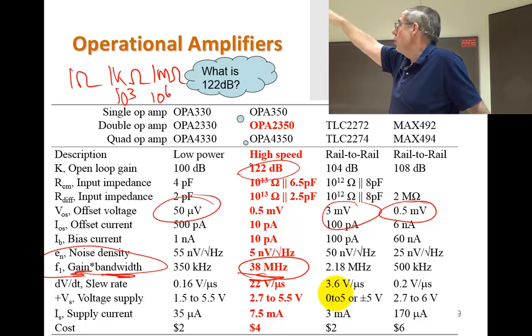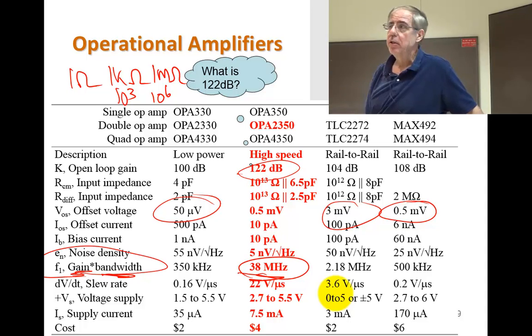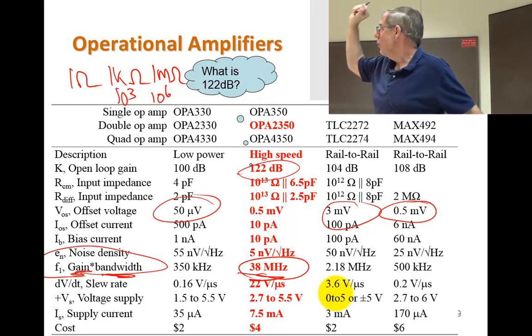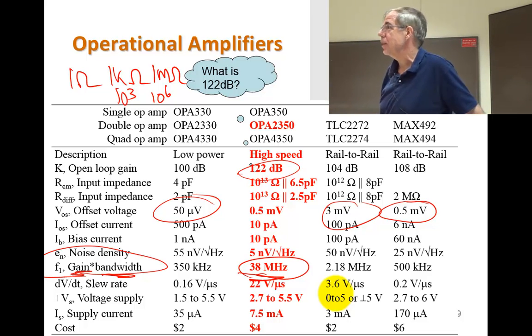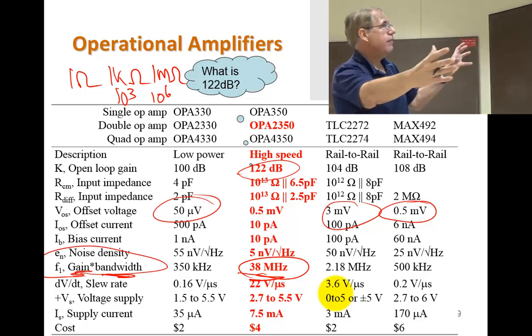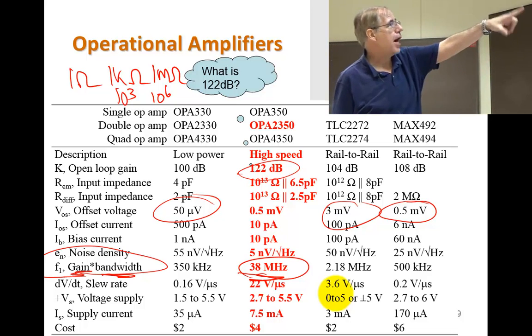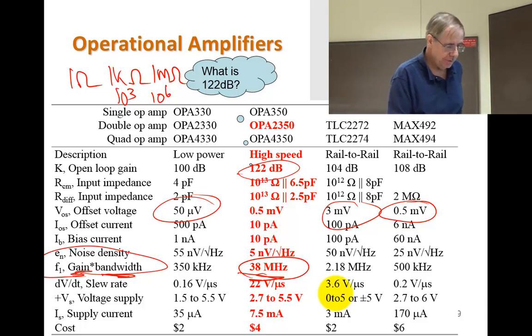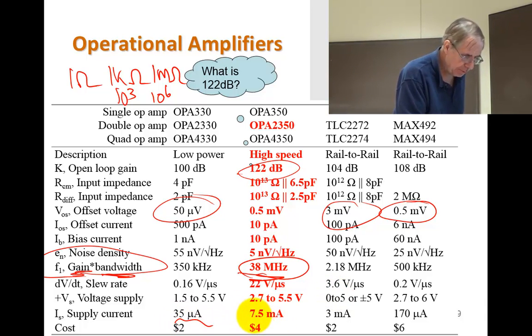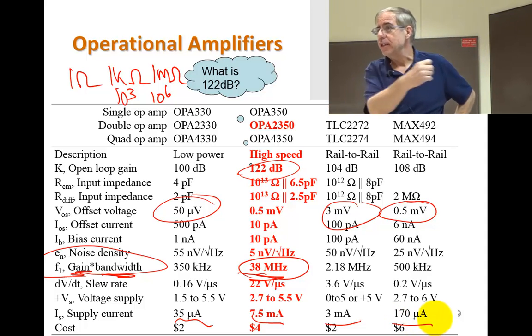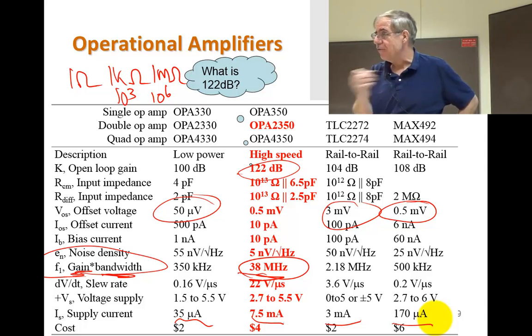Let me teach you one more fundamental thing about speed. And not that speed kills. That's a defensive driving question. Okay, what does speed do in embedded systems in electrical engineering? Takes more power. Okay, so you can actually see it from here. If you compare the amount of supply current down there, you'll see that it's linearly related to how fast it is.